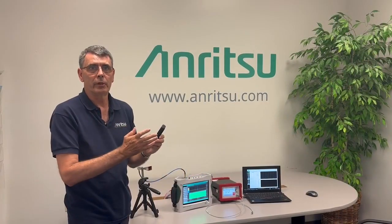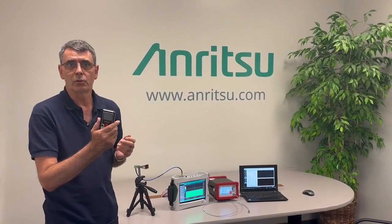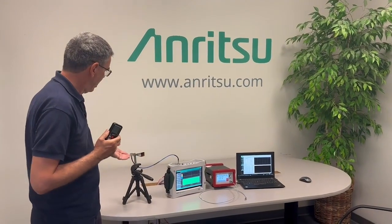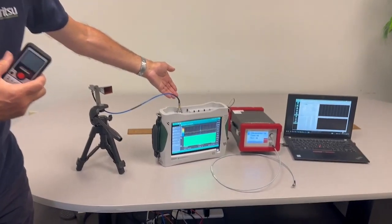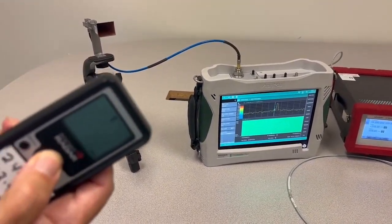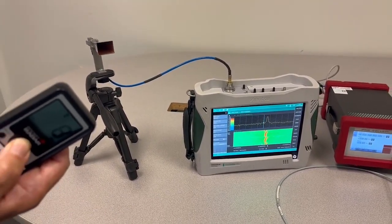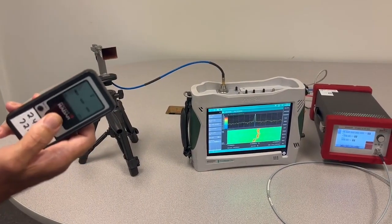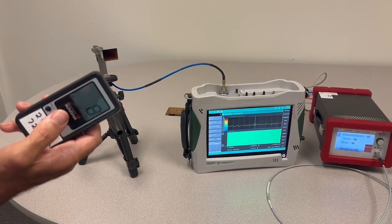I just want to show you what the signal from the pocket radar looks like. This is a 24 GHz radar, the type of radar that's used for measuring the speed of a baseball. I've got a waveguide horn antenna here connected to the input of the Anritsu MS-2090A Field Master Pro. If I power up the pocket radar, we can see the radar bursts on the screen of the spectrum analyzer there. And I power off the radar and the signal disappears.